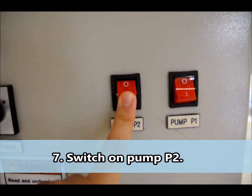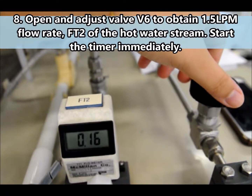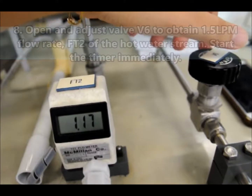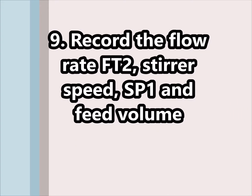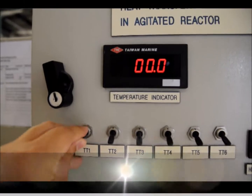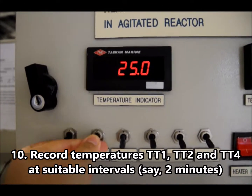Switch on pump P2. Open and adjust valve V6 to obtain 1.5 liter per minute of flow rate FT2 of the hot water stream. Start the timer immediately. Record the flow rate FT2, stirrer speed SP1 and feed volume. Record temperature TT1, TT2 and TT4 at suitable intervals.